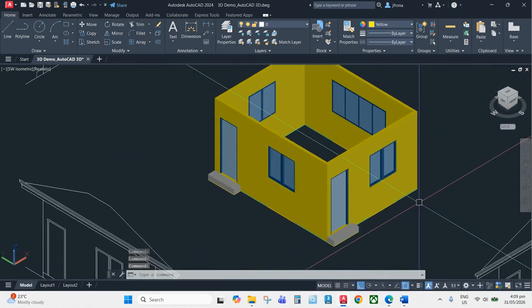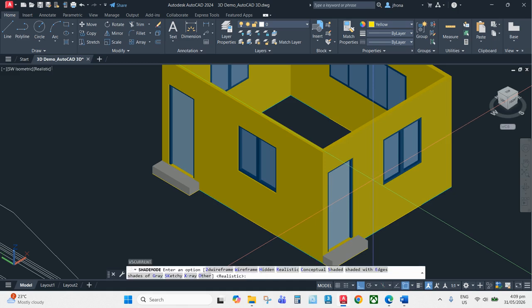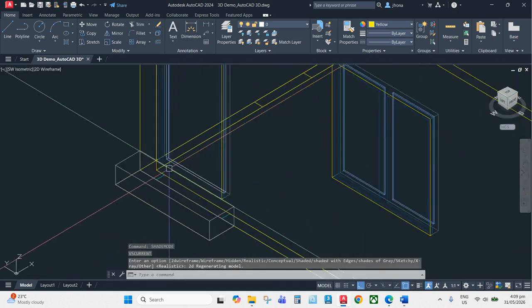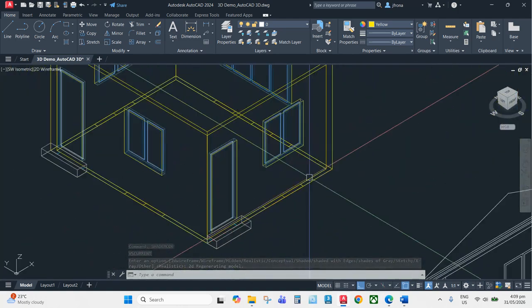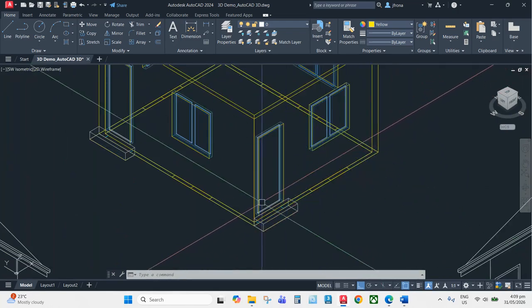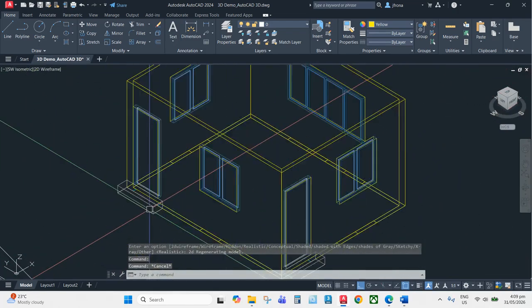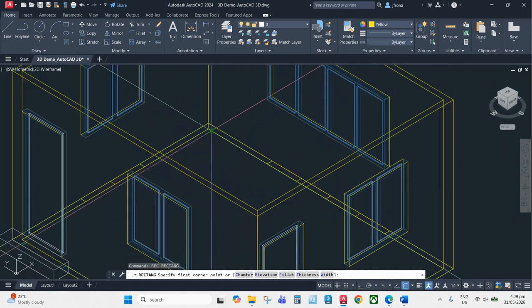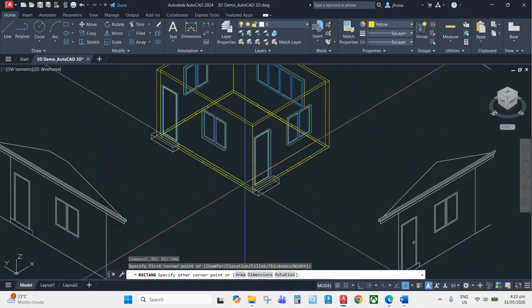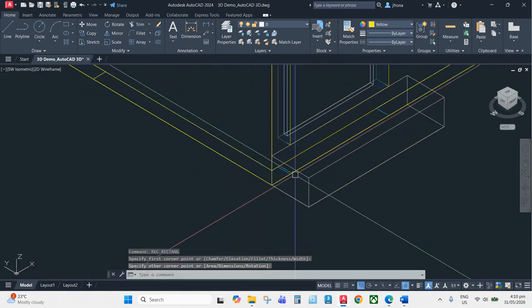Okay. We're now going to create the floor. So since I cannot see inside, we're going back to shade mode, 2D. And then I'm going to use a rectangle inside. Alright, so the only problem here is how am I going to select my line when it's created? So this is the right one.